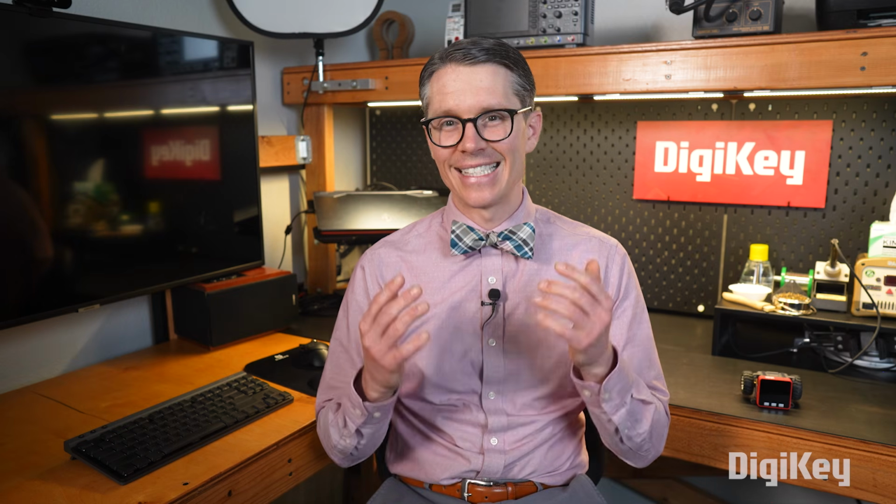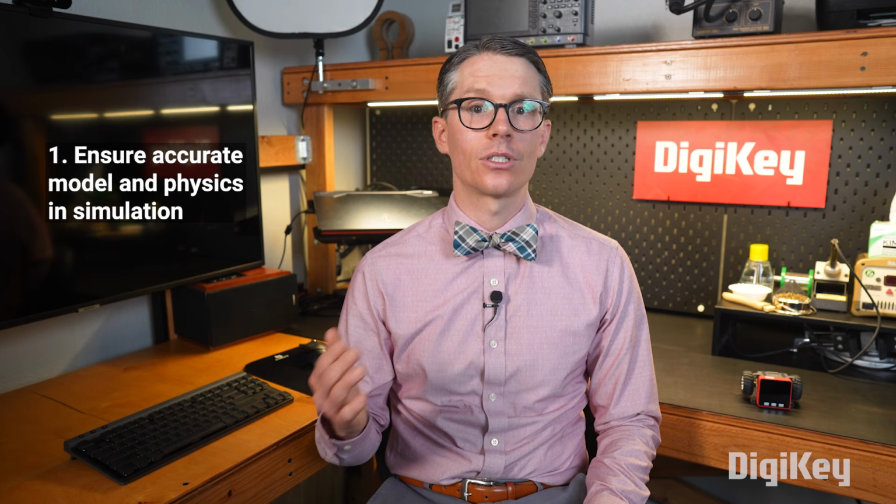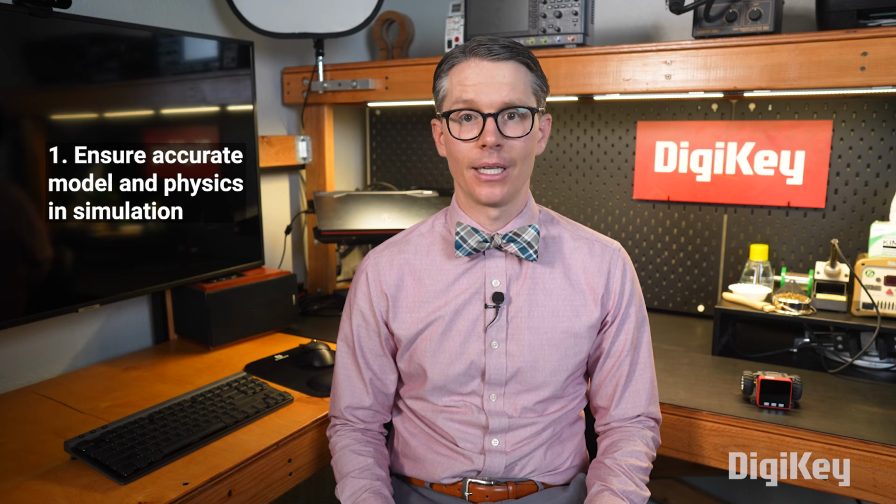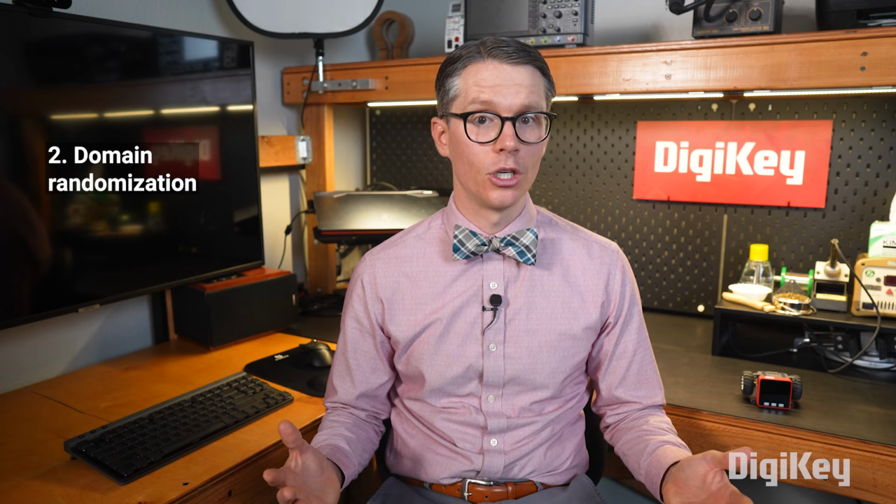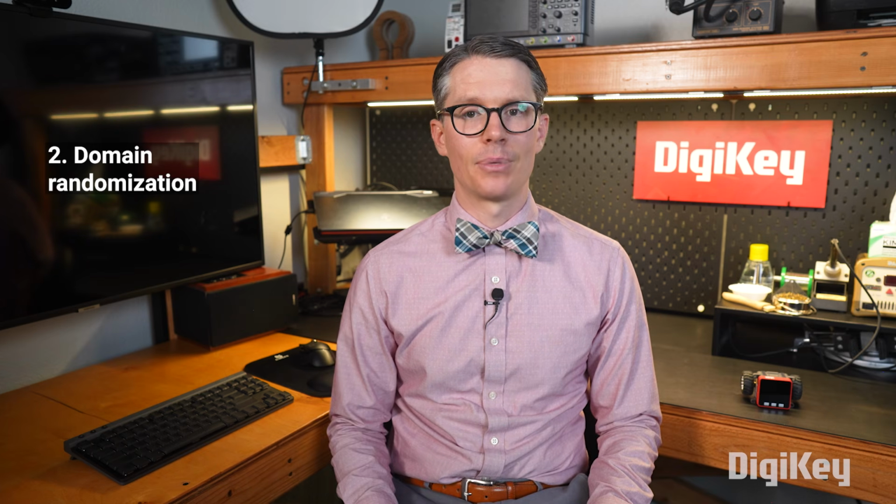It could be due to noisy or miscalibrated sensors, inaccurate motor torques, noisy environments, the robot not being modeled exactly correctly, and so on. There are a number of ways to address this. I know that some robot shops, like Disney Research, spend a lot of time modeling the robot exactly as it appears in the real world and ensuring the physics of the sensors and actuators are accurate in simulation. Another common way to handle this gap is to use domain randomization, which we'll explore in the next episode.